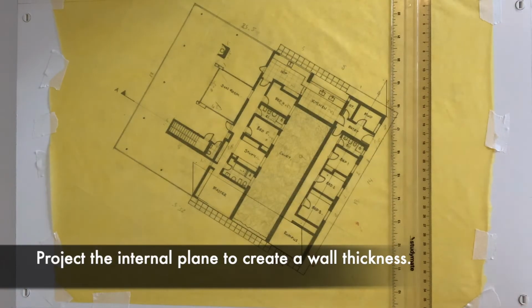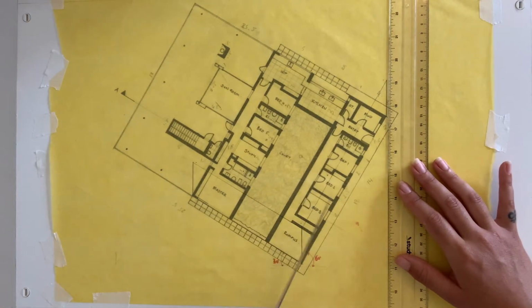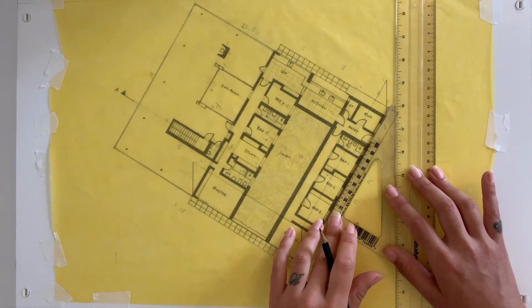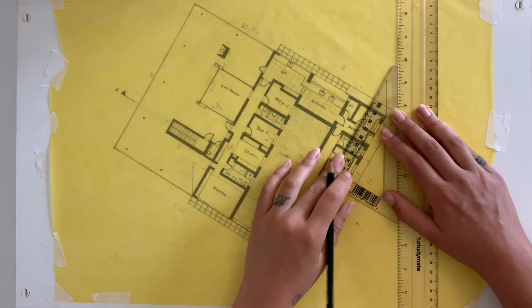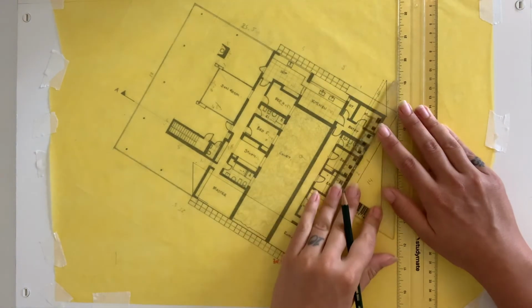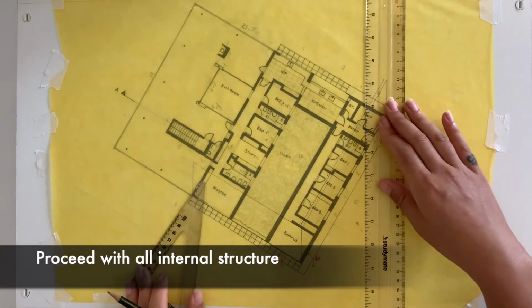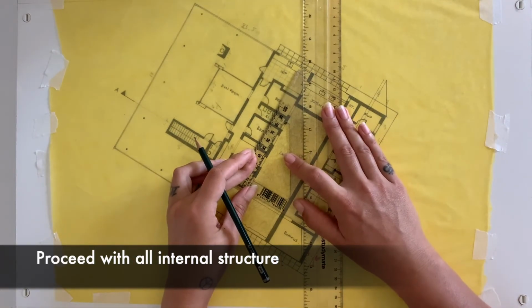We repeat that on each corner to give that wall thickness, and then we will do this with our ruler again, find the right angle. In this instance it's the 60-degree reference. We slide it up and down our T-square, lock it into place, align it with the other line, and then we get a nice true 60-degree angle. And we repeat this in the other direction with our 30-degree angle. You just slide it up and ensure that those 2 points meet.